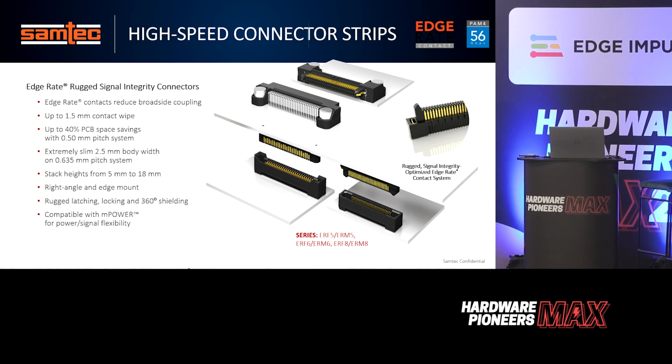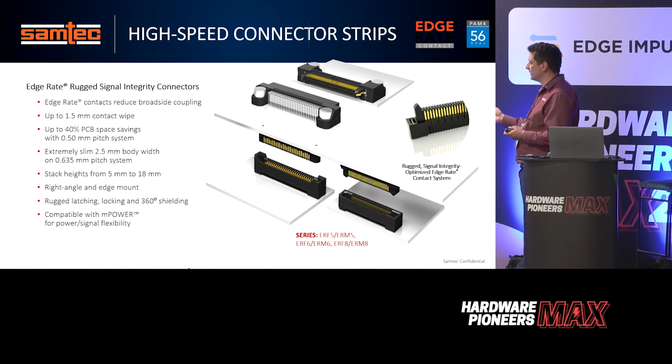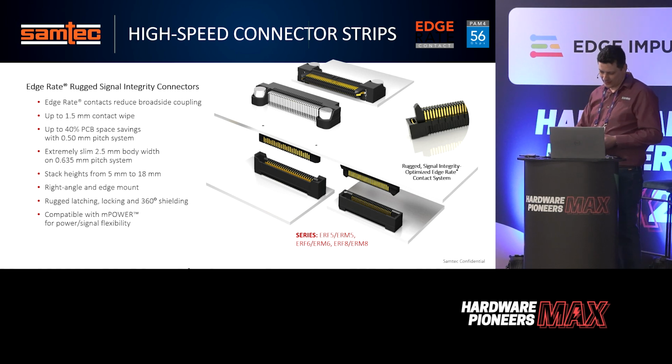We can even bring shielding into the connector, so if you are in a very noisy environment, that will be helpful for you. And again, similar flexibility in terms of stacking height and configuration, micro backplane, right angle to vertical, and coplanar connections. This one is a really good connector. It actually performs better in a coplanar connection than the C-ray connector. Obviously, with the C-ray, as you get that many columns, the right angle creates a constriction of the pin, which creates a lot of reflections within the connector, so it's not as good for high speed as this one that is very small. The reflections are really low on this connector, so you can get easily to 25 gigabit in a coplanar connection with this system.